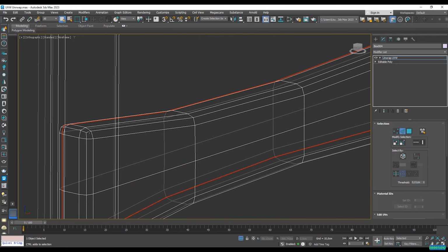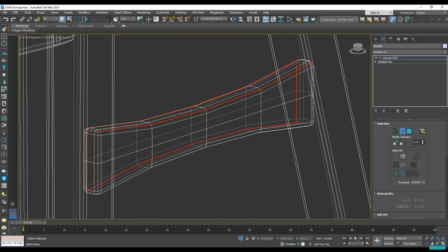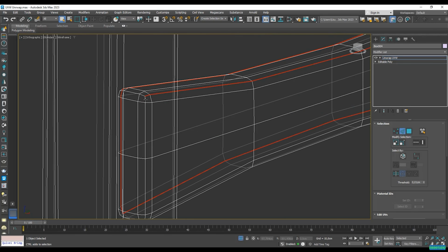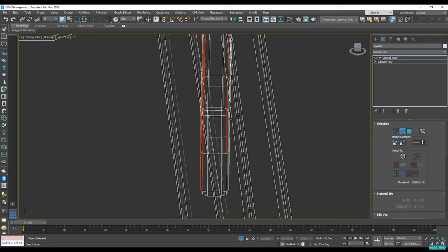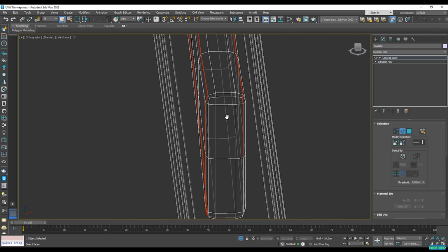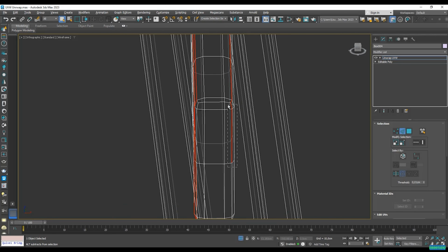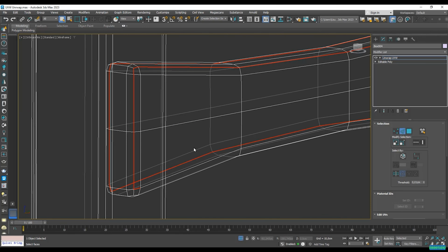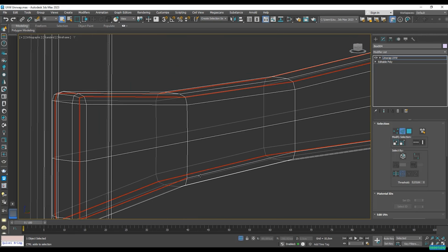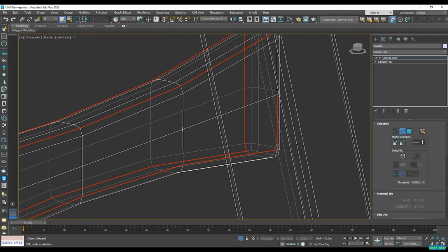Now the other face, the same way. I can actually double click just to loop this bit here. Make sure that we leave it as a symmetry. And I actually didn't select this in the right way. And there's actually a symmetry option here. Symmetrical geometry selection, as you can see. However, this can slow down your PC in some cases, so I prefer not to use it. And because I am also recording, I don't really want that to happen.